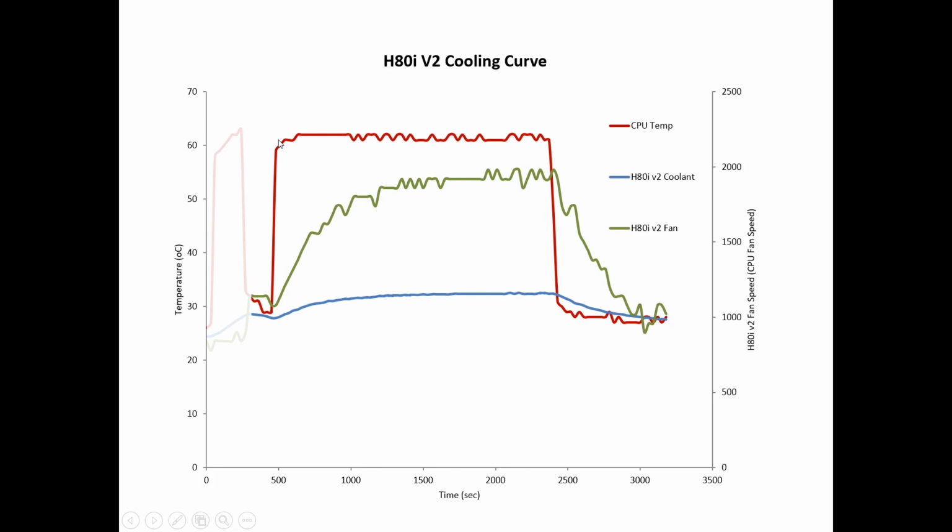So that's running the processor at 100%. Now here's the temperature of the liquid cooling medium, the thermocouple, in the CPU cooler system. And you can see that because the processor is running at full pelt, that slowly starts to increase in temperature until it gets to some plateau level here that you see. And basically, that cooling curve on the water cooler holds that CPU at 62 degrees very steadily over that period of time, which is about just over an hour maybe.